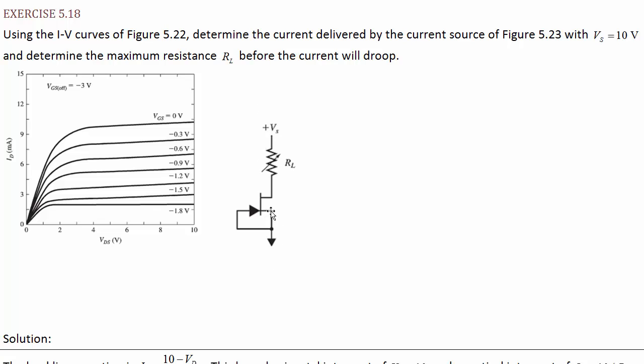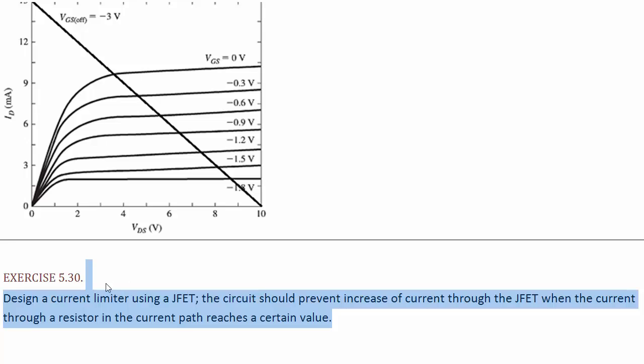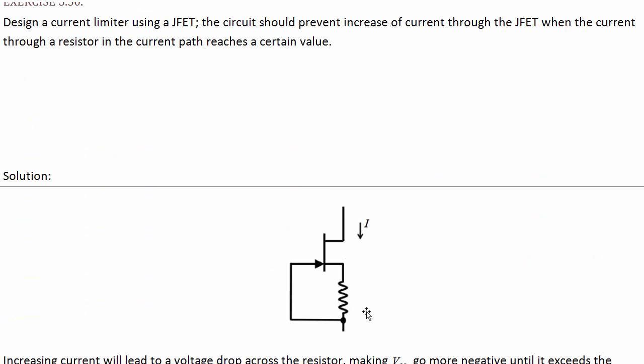So this is going to have a fixed current going through it, no matter what the resistance value is here. This one, we want to just allow whatever current until the current tries to reach a certain value, and then we want the resistance of this element to shoot way up and stop any current. Well, here's a way to do that.